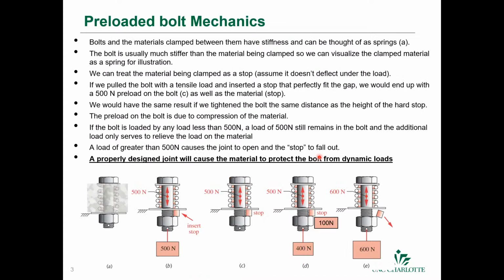Now, bolts and the materials that they clamp between them each have a stiffness. And so you can almost imagine that the material that's being bolted together is acting kind of like a spring. The bolt is almost always a lot stiffer and harder than the material that it's clamping. And you can treat the material being clamped as a stop.